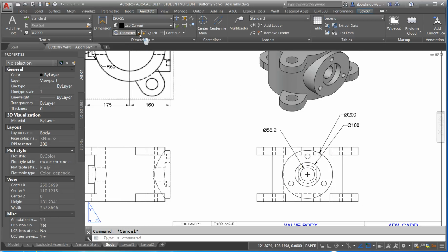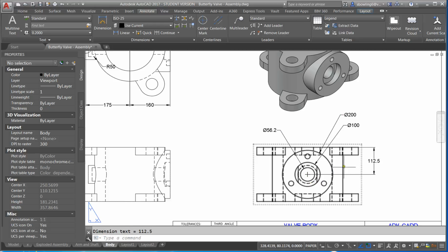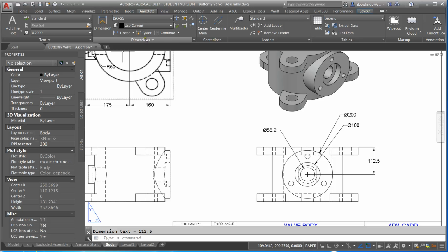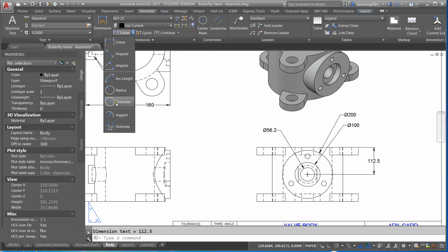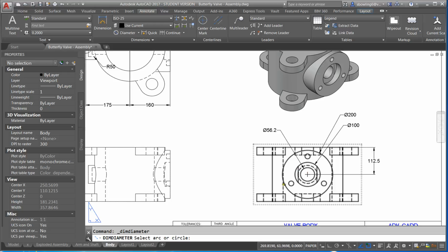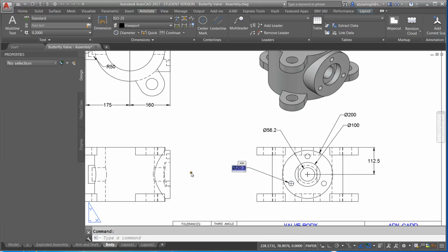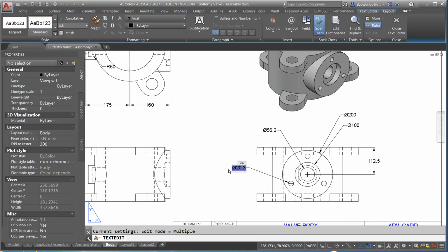Now, you're also going to measure linearly from this end point to the center. You're going to use a dimension line. And I'm going to click on the circle. Now here's the other thing that you can do. You can actually come in here, double click the text, hit the end key so you can start typing. So you go 3 places 15 deep.